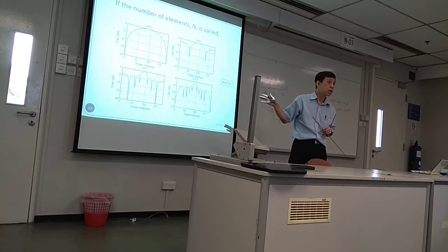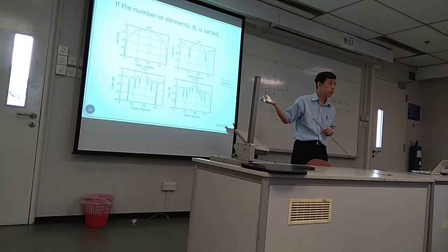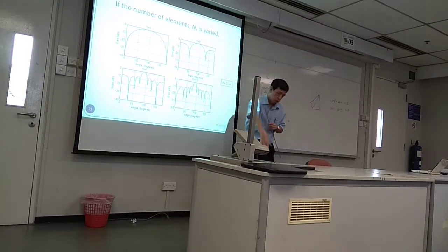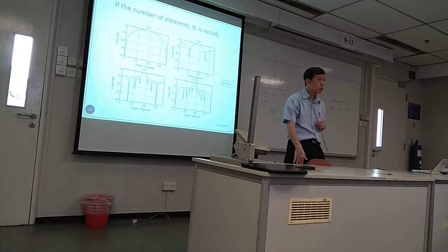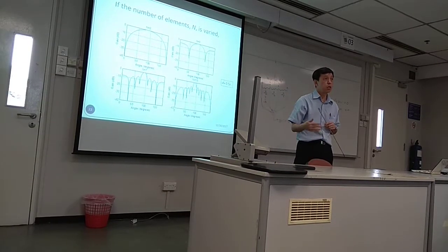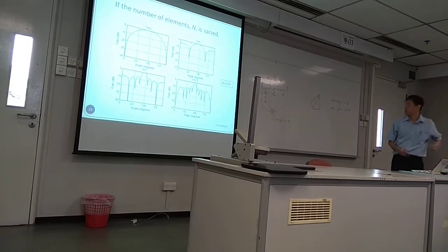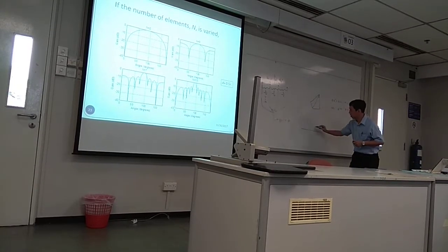Because of my plotting, the resolution is no good. You follow? So this point supposedly should go to minus infinity in dB. And if you plot it in terms of absolute value, then this is what you see, appearing as a sinc function.